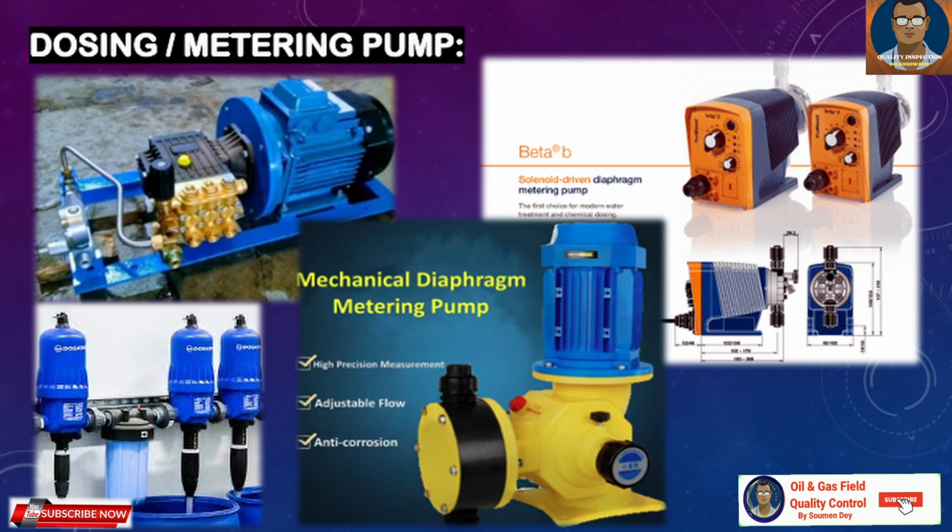A dosing pump, also called a metering pump or dose pump, refers to a positive displacement pump designed to push a chemical or similar substance into a flowing gas stream or water. These pumps are usually small and offer accurate flow rates with maximum control. They are an essential part of the integrated metering system developed to perform automatic chemical dispersion. Dosing pumps enable dispersing certain amounts of fluid while also maintaining the flow.